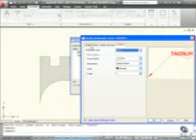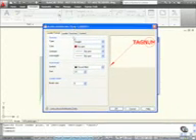So let's go to leader format first. Leader format, I've got a straight leader, which is here. The color is by layer, so it's adopting the leader's layer color. Line type, by layer. Line weight, by layer. So I'm using that by layer option. The arrowhead symbol, closed filled arrowhead, 3.5 millimeters on my millimeter drawing, and the break size there is 5. So the break is this bit up here. There's a little break if you have multi-line text, for example.